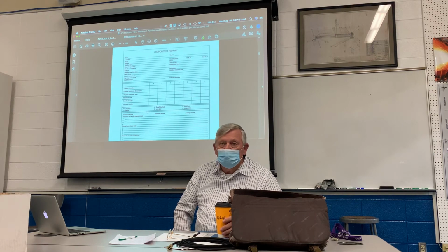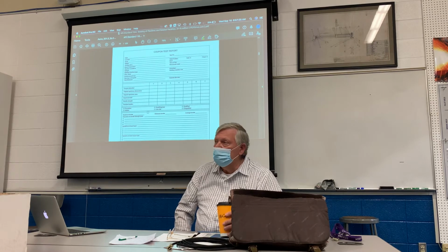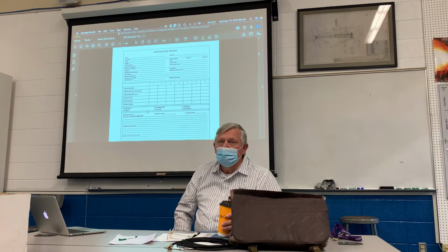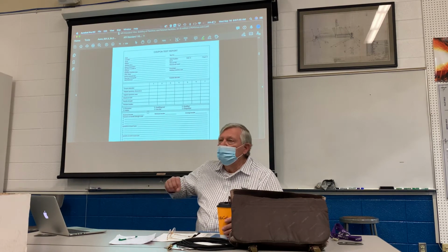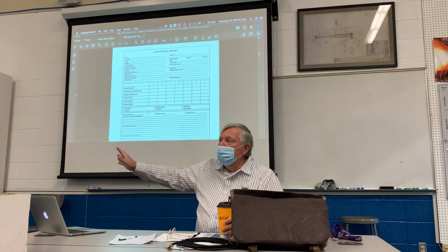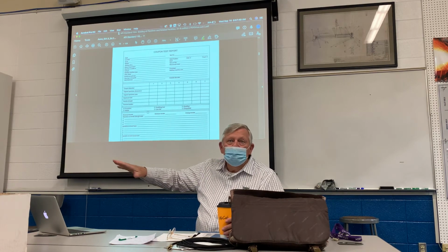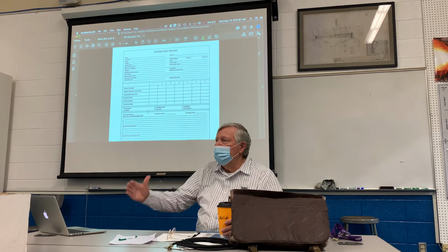Some of the tests that they've come up with for this can easily take you 2 days nonstop. The old Chevron test that was given in Wyoming for the longest time was a 20 on 20 half-inch wall butt weld, followed by a 20 on 20 half-inch wall branch test. And it was an endurance test. You couldn't go home, you couldn't take a 3-hour break. You couldn't go do anything. You had to start that test and you had to finish that test.